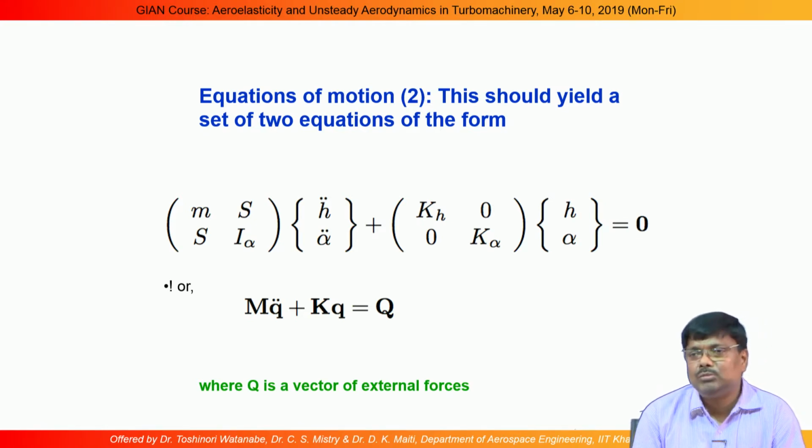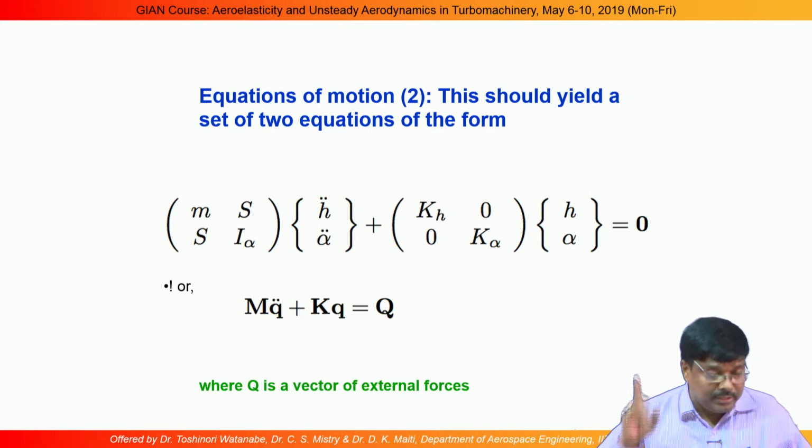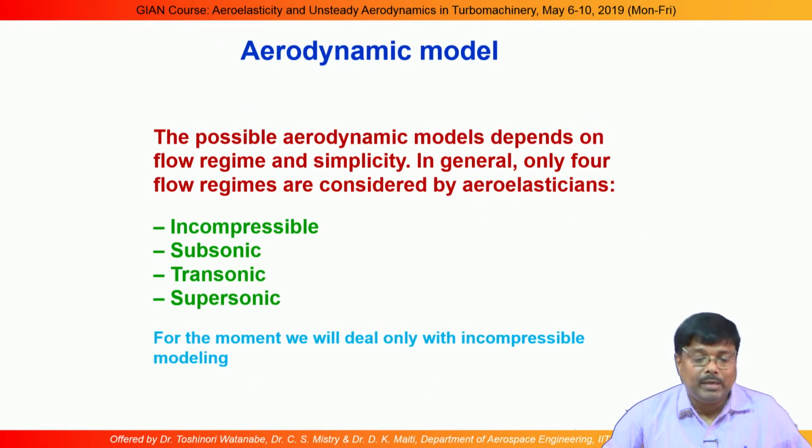And what we usually do, we take the first few modes, those are the deformed shapes, to make the calculation of aerodynamics, and that way it will come as the modal aerodynamic load from the unsteady aerodynamics. Okay, I will proceed, then I will show you another important part.